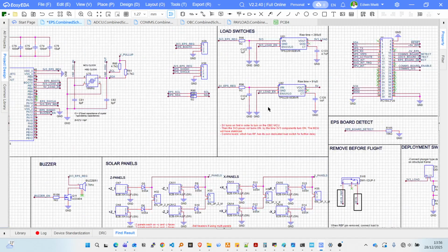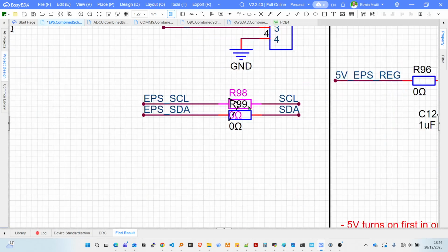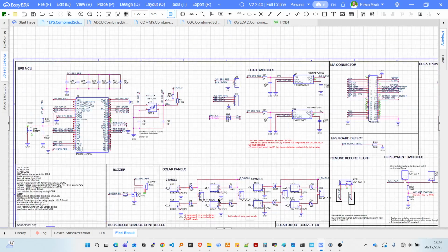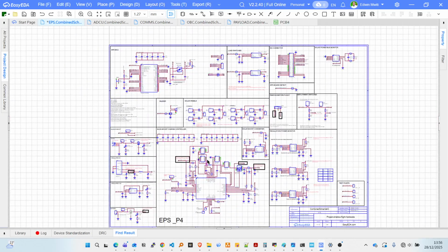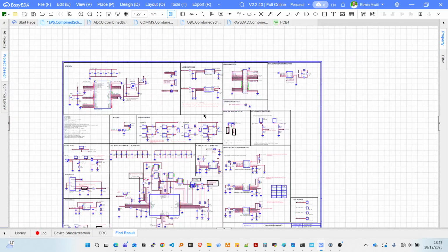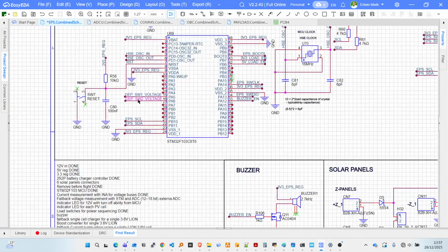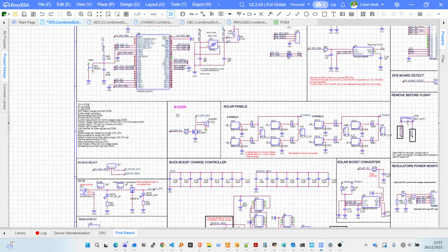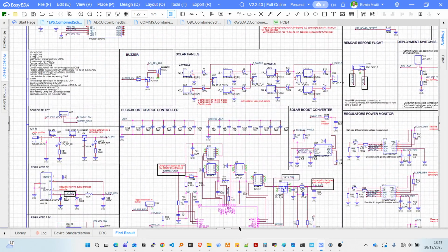Or if there's a bus contention, I can desolder these two resistors and just read the EPS from this IC using this STM32, and then send the STM32 packet to the OBC via these two lines, right? But since it's I2C, I can just chain those components together. There's no problem with that. Right, so we have data from this point.